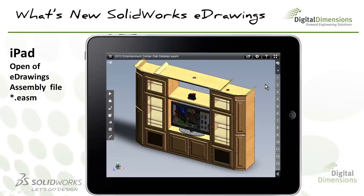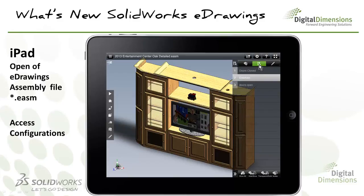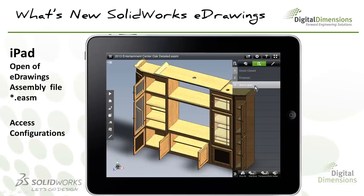And from the assembly, just like standard eDrawings, I can go ahead and take a look at the assembly tree as well as the standard views. And this time around, I will actually access a configuration. And if I wanted to switch configs, just click the configuration you want to show. And then if that configuration had an explode on it, you could toggle the explode.